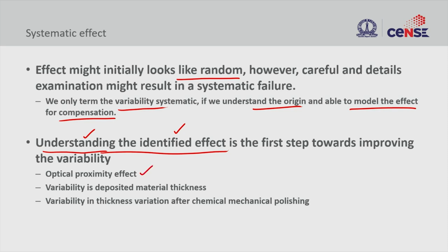So the variability could be optical proximity effect, which needs thorough investigation, and also you could have thickness non-uniformity during deposition, and this is a plasma process or CVD process where your flows are not proper, your wafer placement might be off. So all this could result in variability.